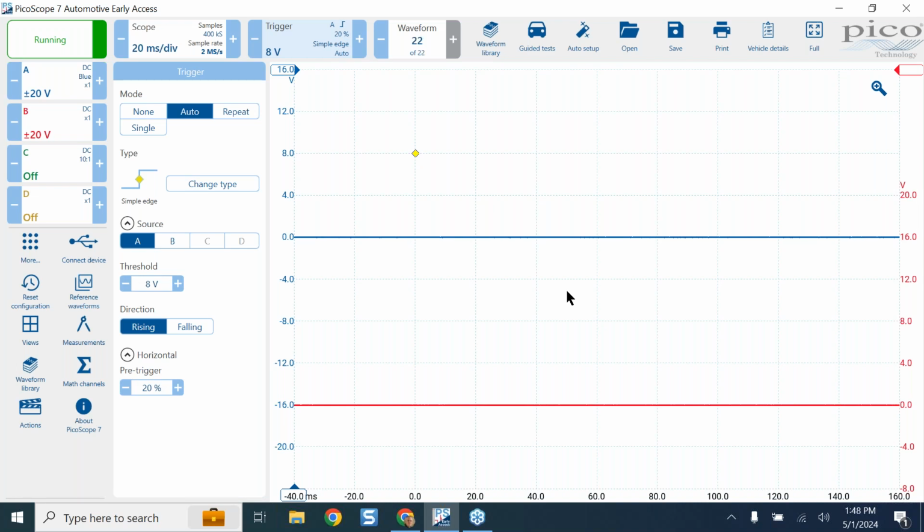So trigger stabilizes the pattern. It is manually set by you, and you have to verify what source, what channel you're going to be on, and verify the level where you're going to put it, the slope or the direction, and how far you're off on the left-hand edge. Triggers really never change. It's really for us. We might have changed the name slightly, but not much.